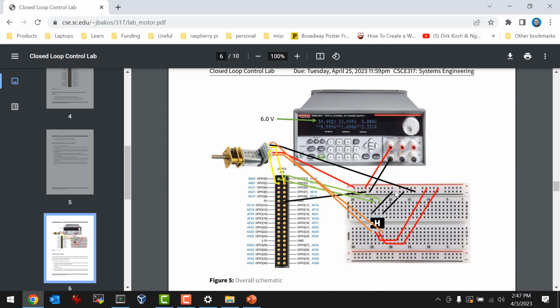Okay, and then the outer two pins on the bottom are going to go to your M1 and M2 on the motor. That's OA and OB. And IA and IB are the inputs, and those are on the top two middle pins, and those are going to go directly to the FPGA. So that'll allow the FPGA to control IA and IB. And by controlling those, you're controlling the H bridge, and the H bridge is what actually controls the motor.